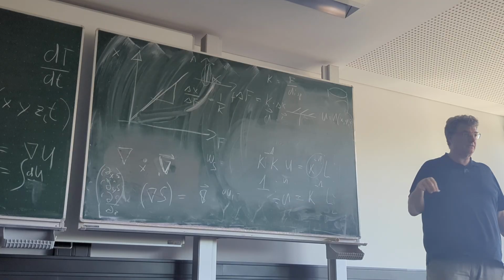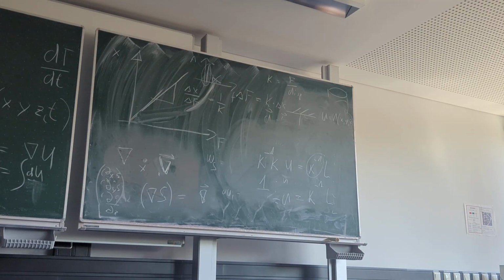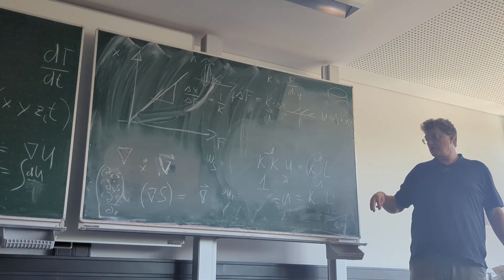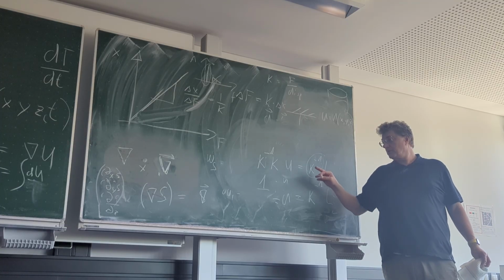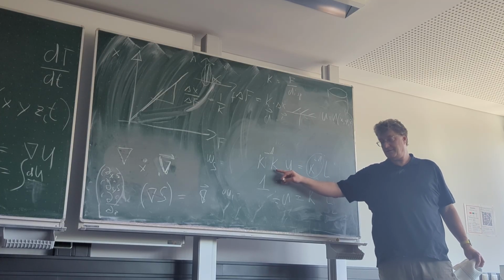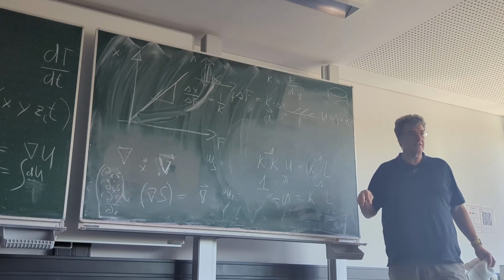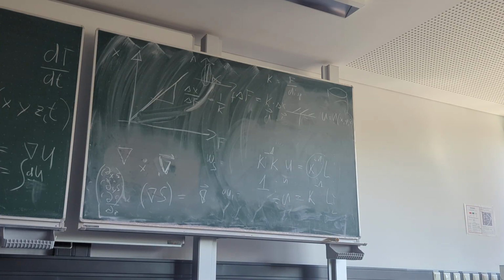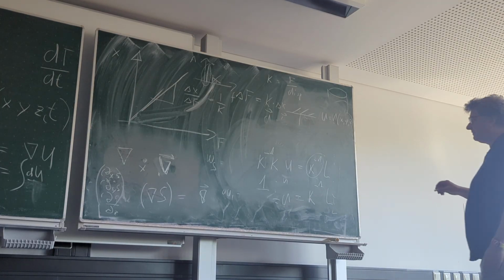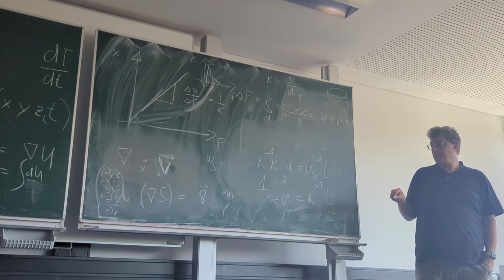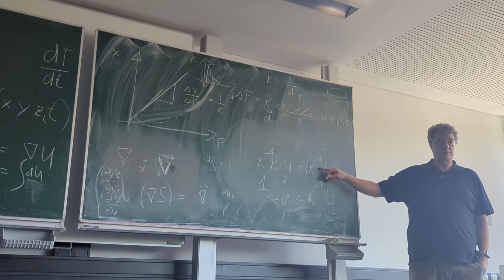And again, this is something the computer is perfect for. If you use MATLAB, and we will do it in an example, we actually do exactly this procedure. Let COMSOL calculate the system matrix, and then we use MATLAB to do the inverse, and then we just let MATLAB do the multiplication, and then you can solve in MATLAB the finite element problem. So this is one of the numerical methods how to solve the problem. Just calculate the inverse matrix.